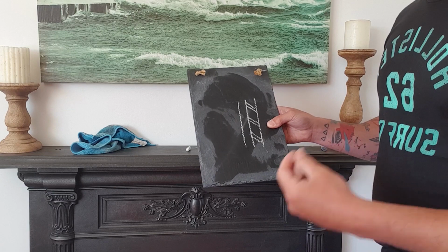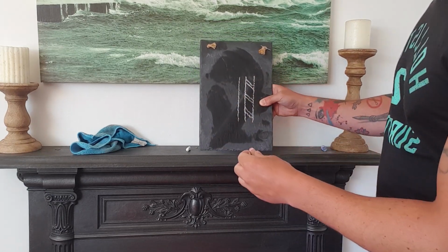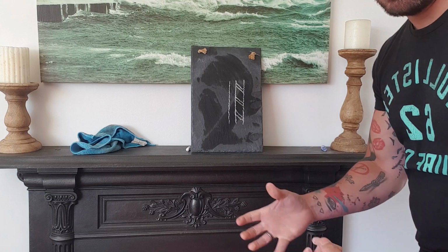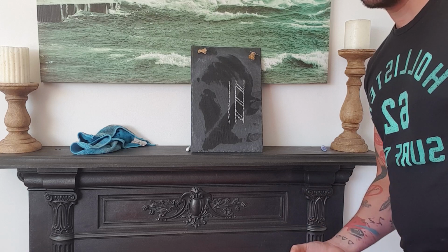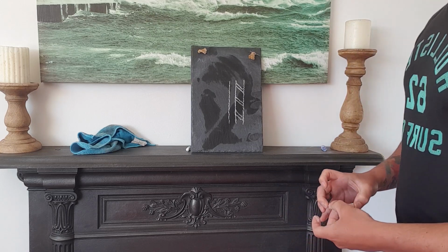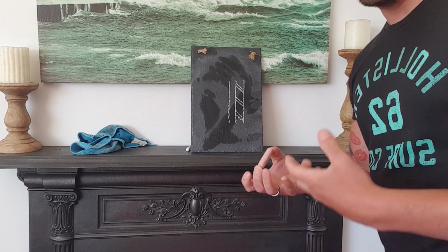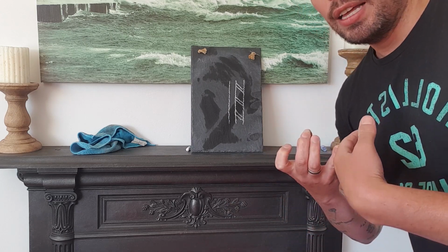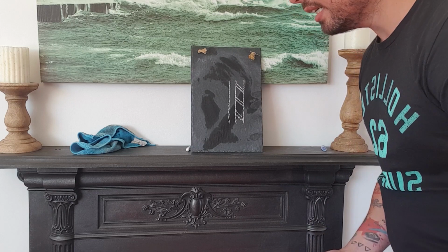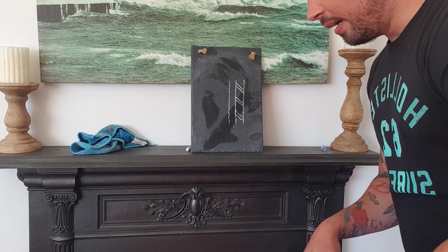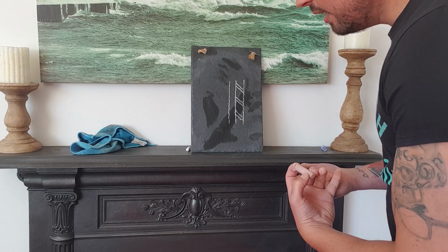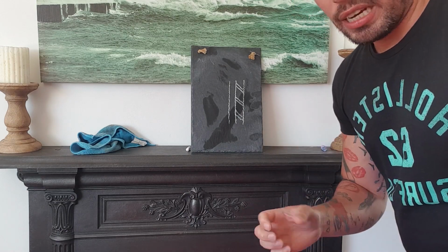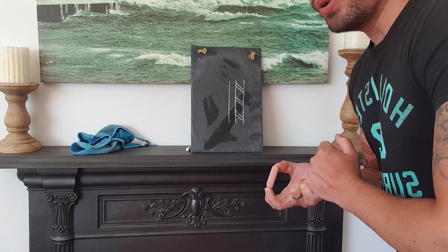Now, we get our insulation thickness from SAP assessors and acousticians. These people, they collect the data from the site, the various things around in the site, and they come up with a value called a U value, which gives us our thermal conductivity rating and how good of a performance our wall has to be. And an acoustician will tell us what type of decibel rating the wall has to achieve, and for airborne sound. And we then collect that data.